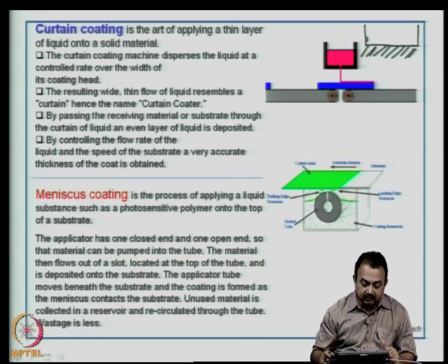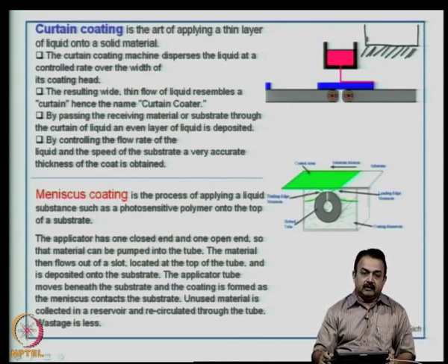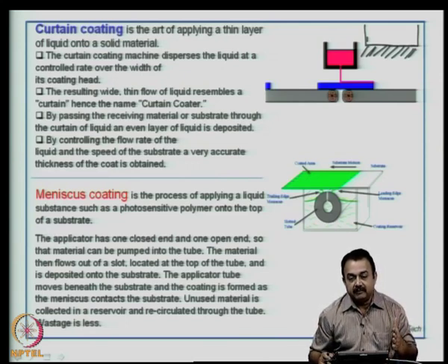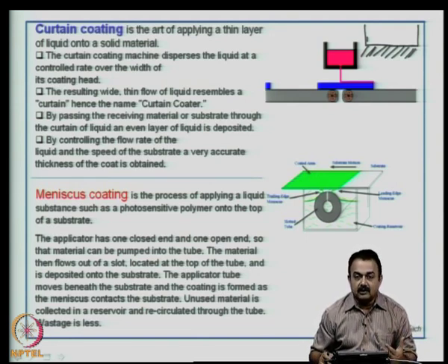All of these become very important to get a uniform thickness. But the first hand information that I can give is curtain coating will definitely give you much better thickness control. You can get thicknesses even up to 15 to 20 microns, which gives you an idea of how you can utilize this technology for high density interconnect applications.